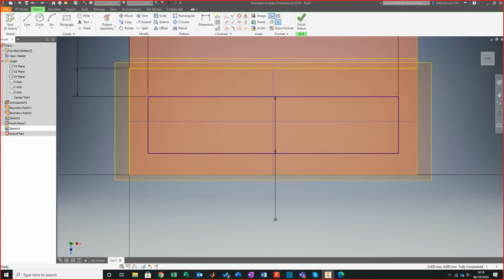Oh, I forgot to do that. So I just want to remove my construction tool and bring a corner rectangle and draw it straight across like that. Now all I'm going to do is go, not mirror. Here I've got symmetric. So I'm going to go this edge and this edge, and this edge.